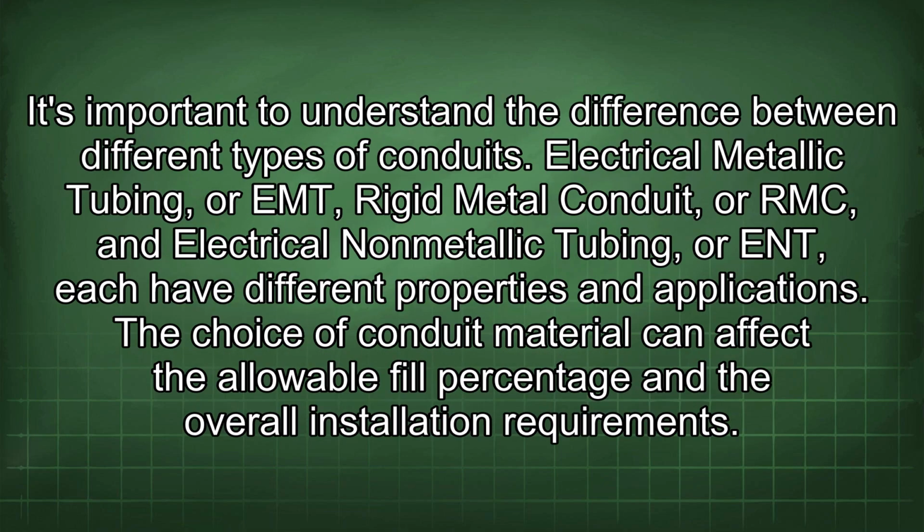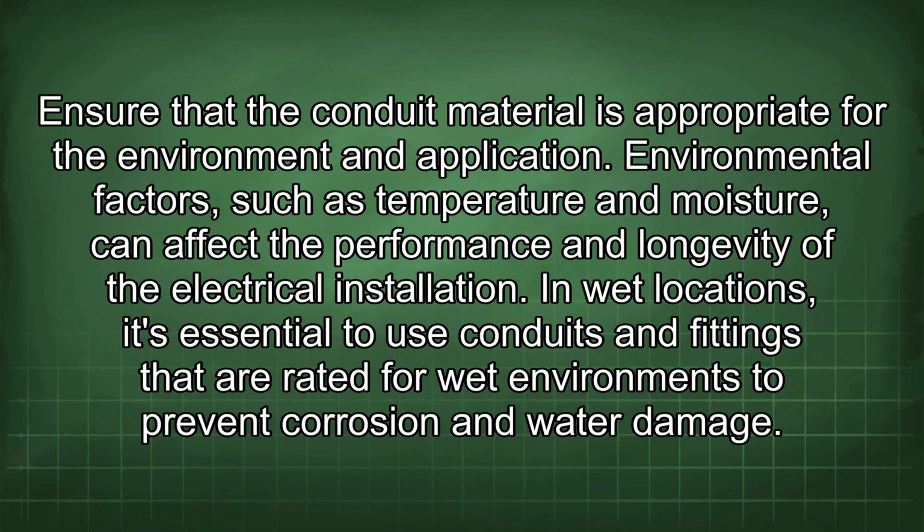It's important to understand the difference between different types of conduits. Electrical metallic tubing, or EMT, rigid metal conduit, or RMC, and electrical non-metallic tubing, or ENT, each have different properties and applications. The choice of conduit material can affect the allowable fill percentage and the overall installation requirement. Ensure that the conduit material is appropriate for the environment and application.